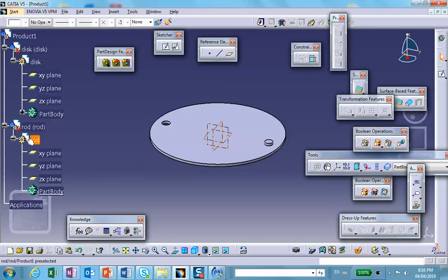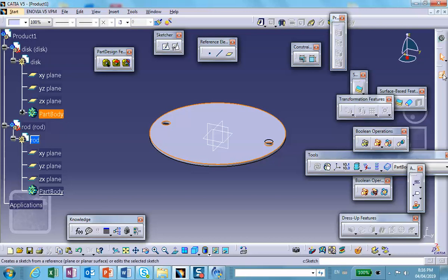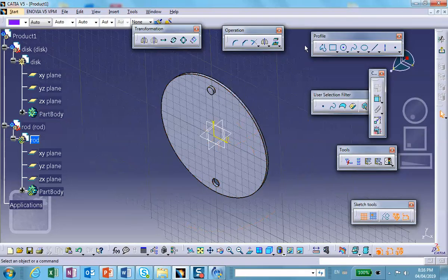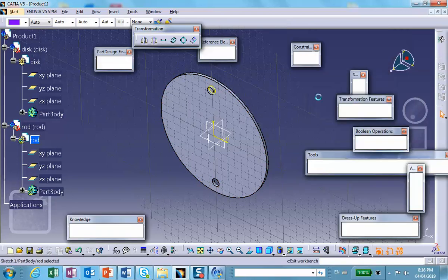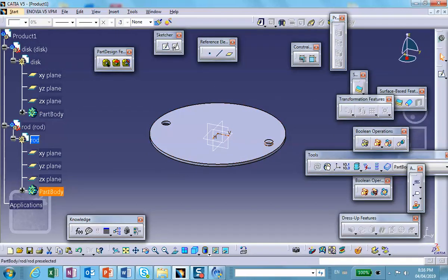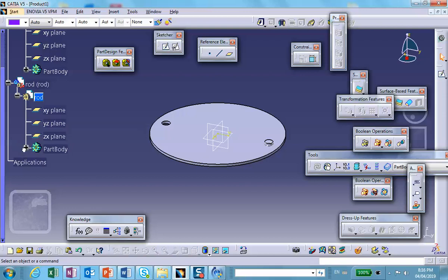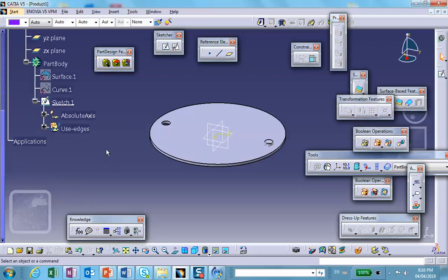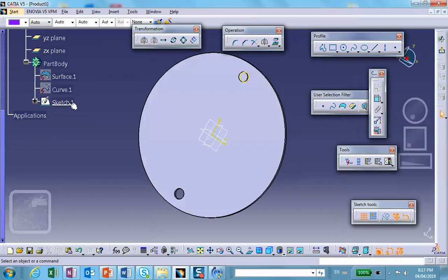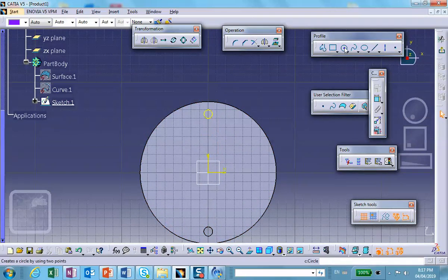Okay. On that plane, I will sketch. Why don't I project that circle? Because the rod is actually going to be inserted in that little protrusion, so we're going to draw the rest of the rod. Okay, so that's your projection. Then we go to that sketch and complete the rest of it, something like this. The original orientation is not important because it is irrelevant to the problem.